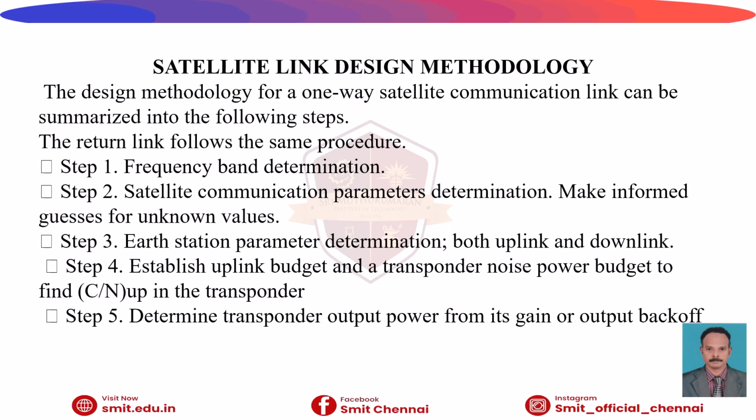So the satellite parameter determination involves the satellite EIRP, the satellite gain, the satellite footprint. Footprint is nothing but the coverage area. These are the three prime factors, as well as the transponder bandwidth, as well as the satellite position also. So these factors must be very important.